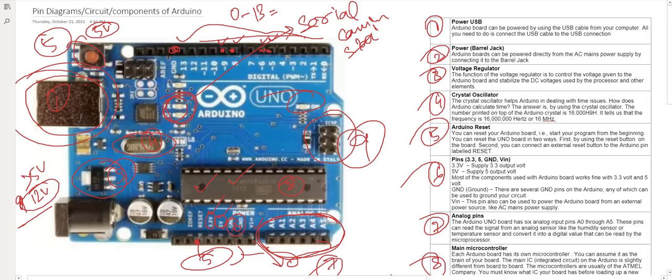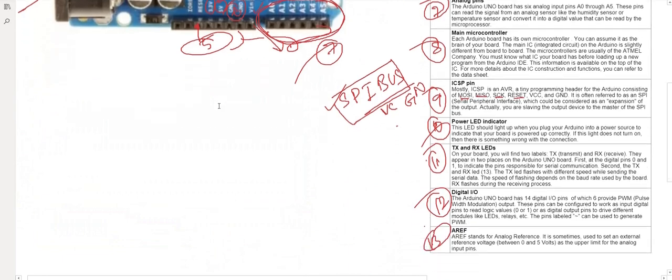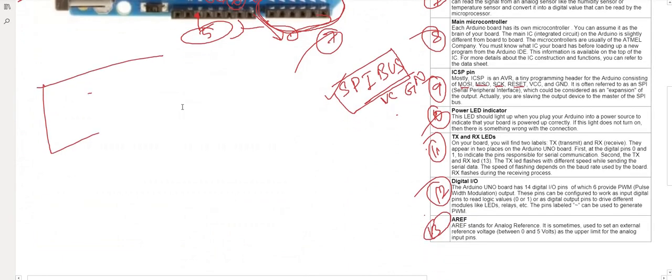And you can see some small components. These are some resistors and capacitors required for the complete IC to work. And these holes are there because it is a multi-layer circuit. When you want to connect a wire from the upper layer to the lower layer, you just drill a hole from the upper side to the lower side and connect both of them.